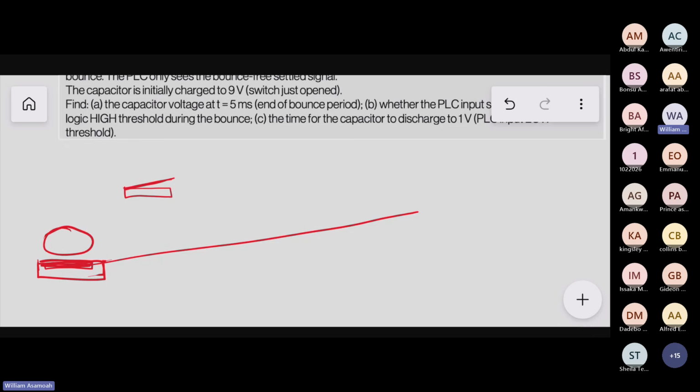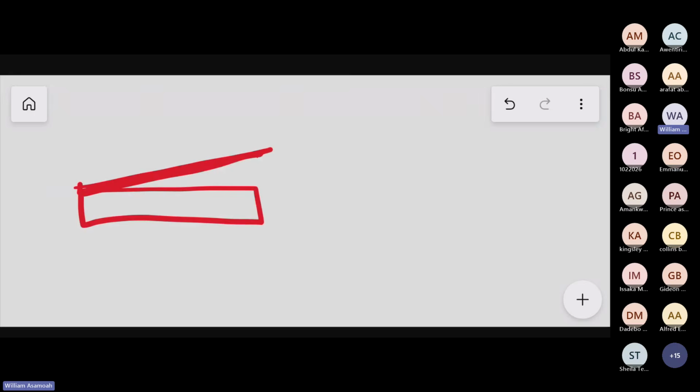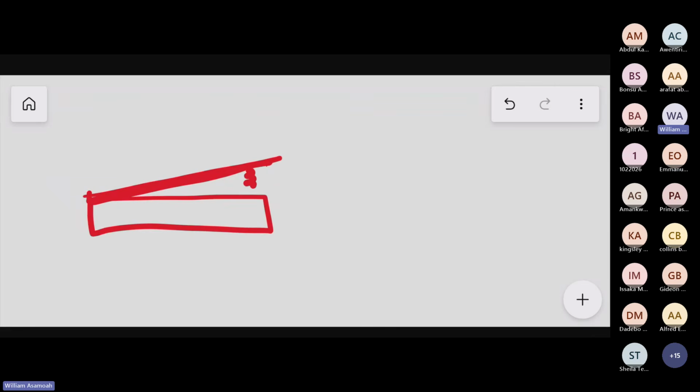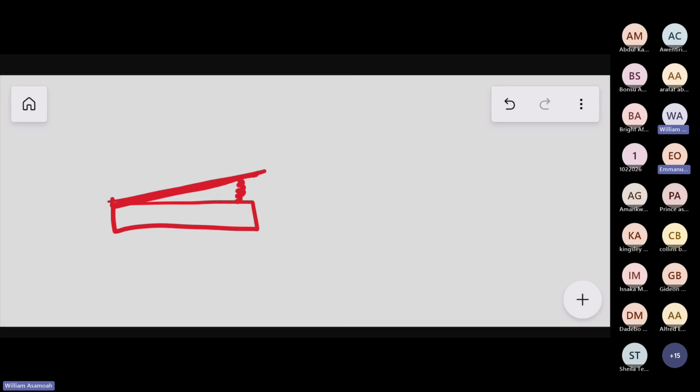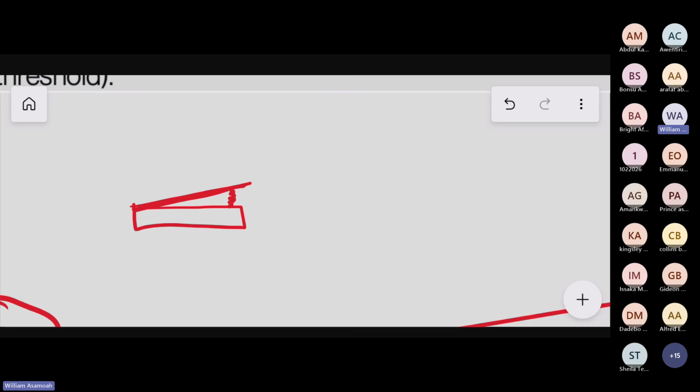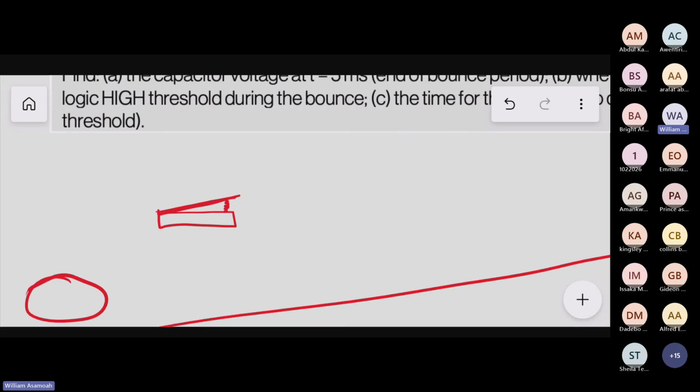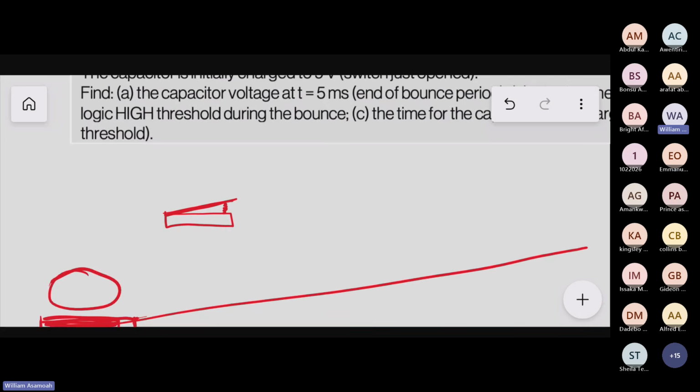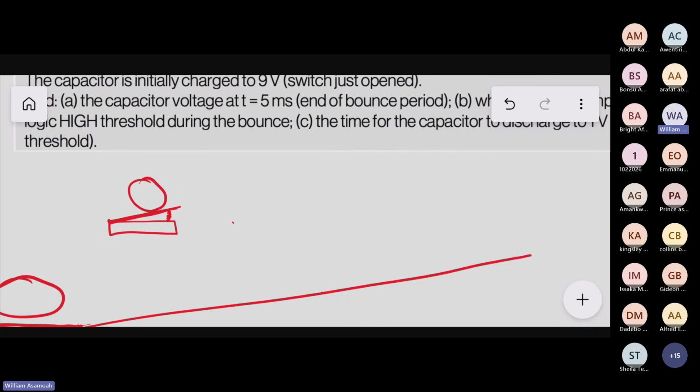So these ones are called contact switches. If there is no object, you know that for these kinds of switches, there will be springs here so that it will stay open if there is no object. Now, when a mass settles on it, when a heavy mass falls upon this thing, the mass will overcome the spring constant. And so the switch would close like this.